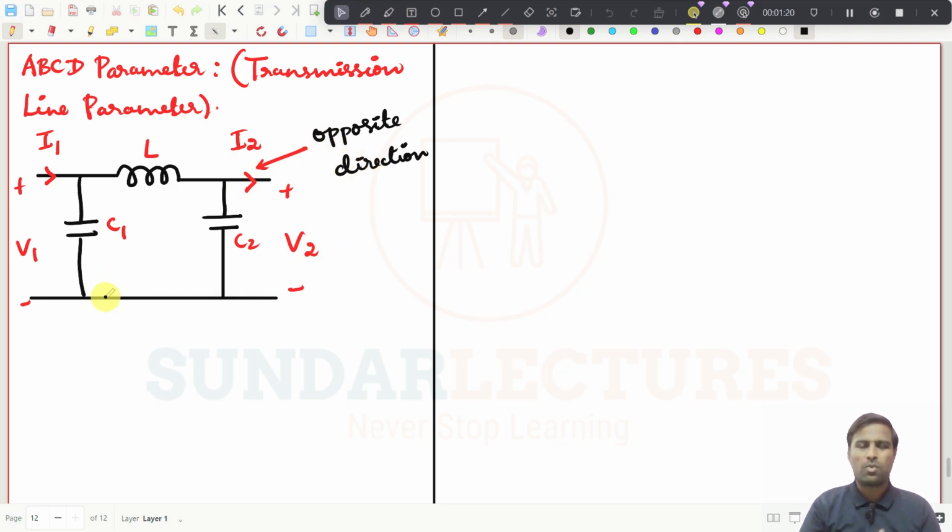Right, now what is this ABCD parameter? These kind of things will be there in transmission lines, and you have to get the parameters to simplify the problems or to understand the transmission line in-depth concepts, right? So now what we will do, we always take the input as this one, which we commonly call the sending end. This is actually the sending end. This will be the receiving end, right?